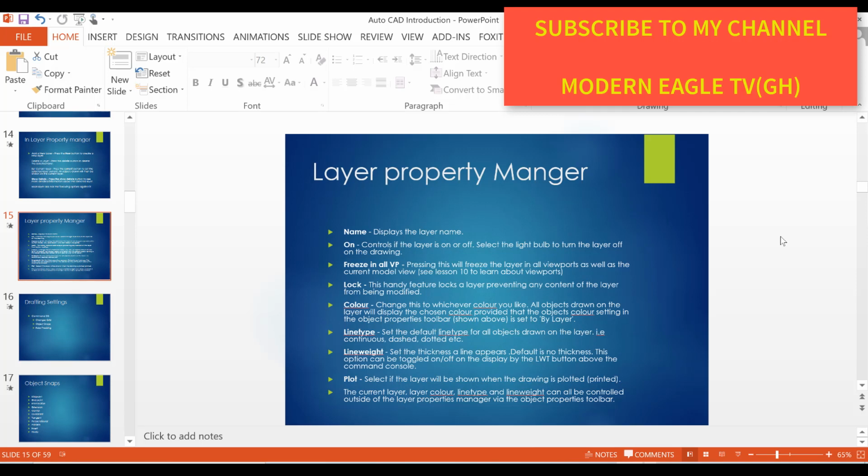Line type: set the default line type for all objects drawn on the layer, that is continuous, dash, dotted, etc. Line width: set the thickness a line appears. Default is no thickness. This option can be toggled on or off on the display by the line width button above the command console.